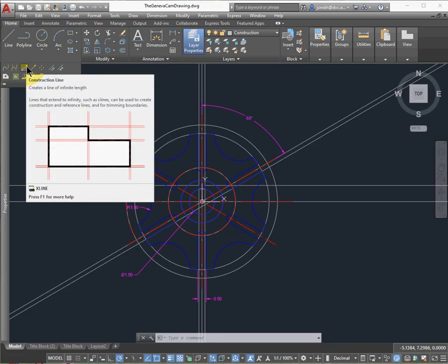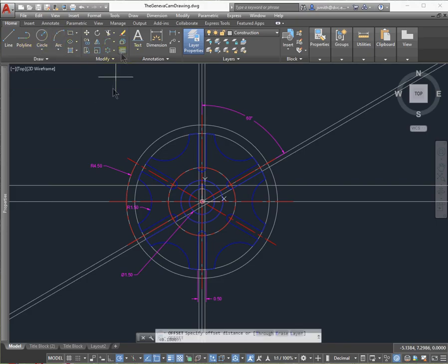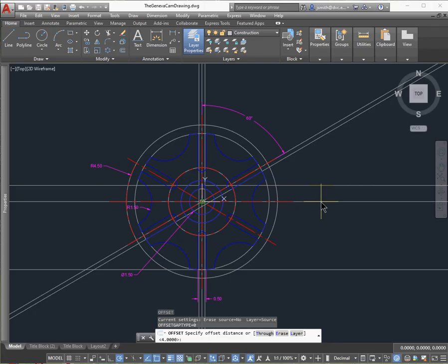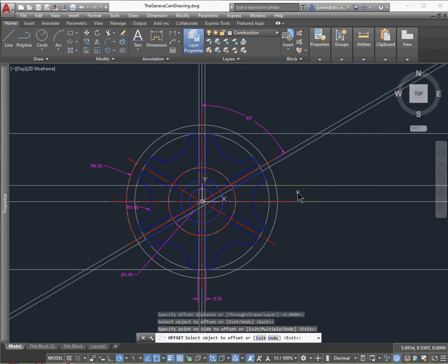I need to determine how far apart it's going to be, and this one's going to be the top here, 4 inches. So I'm going to add these construction lines here. This will help me when I start to do the orthographic views, and I'm going to make the side view to the right of it in a moment.